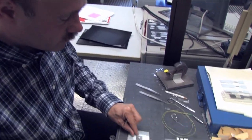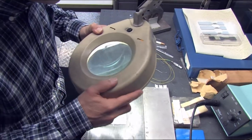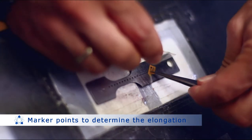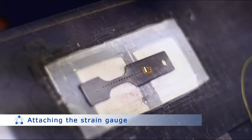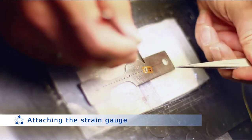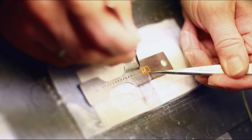To obtain accurate testing data, the preparation of the specimen has to be carried out carefully. This includes measuring the characteristic values, for example thickness, width, and gauge length, as well as cleaning and preparing the surface for the attachment of strain gauges for the force measurement in the section of the specimen where only elastic deformation occurs.